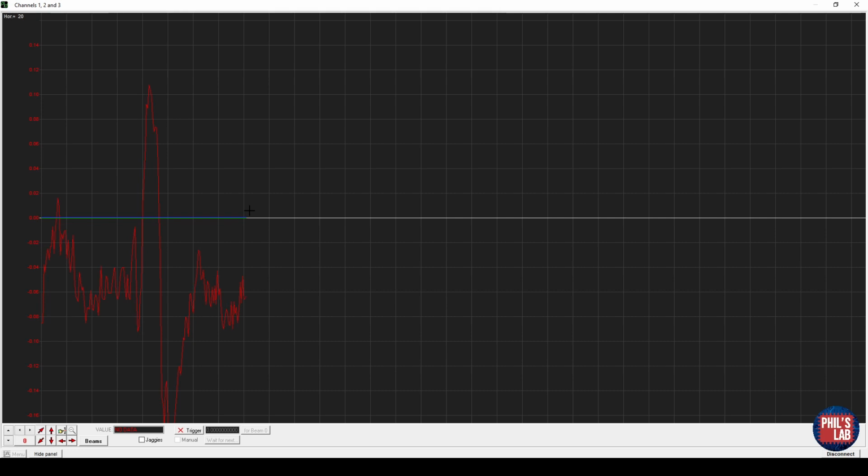And let's just watch this for a while. I'm not touching the board, I'm just letting it sit here, and we can see the random walk this sensor is performing, or the measurements are erroneously moving about our relative altitude. Notice the scale on the left, we have a scale of meters, so 0.0, 0.02, so this would be centimeters then.